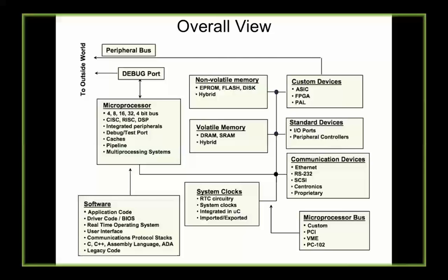The use of debug port or JTAG ports is to fuse the bootloader, or fuse the small OS or firmware on your hardware. So your hardware has a very special facility by which it can communicate to your PC by using a JTAG interface. And what's the purpose of that interface? So that from your PC, you could transfer your applications to the target board. That's the purpose of debug port.